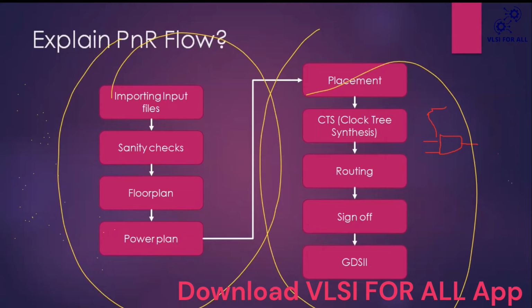I hope you know these things. So the input files are the netlist, .lib, tech file, LEF file, and SDC, and the UPF file is optional.